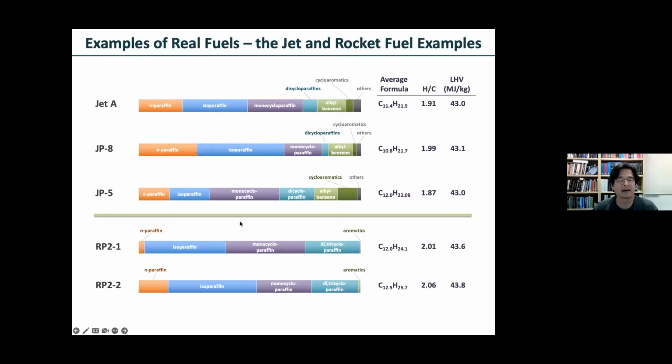Okay. And then also, if you look at the fuels that are rocket fuels, they are isoparaffin, N-paraffin, and so on. Similar composition, except with distribution of the classes of compounds being somewhat different. Now, they do differ in composition. Yet, if you put JP8 into commercial airliners as a Jet A, it burns just equally good. Okay. So the thing that we should look at with this complexity, the first notion we get is because of multi-component mixture, they must be more complex or more difficult to predict their combustion property. And that turns out to be not true, and I'll explain.